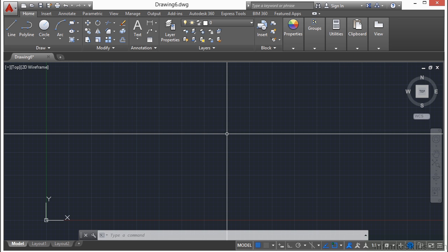When you draw, make sure to know what units you are using. Your units can be anything. It can be feet, inches, meters, kilometers, or even parsecs if you're going to make some kind of space travel map, for example. It doesn't matter. What does matter is that you draw to full or real scale and in one unit. AutoCAD can really only draw in one set of units at a time.